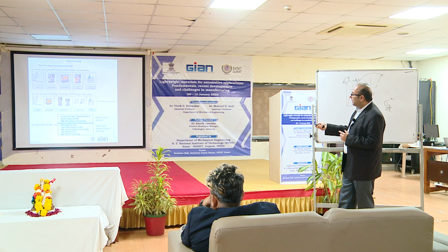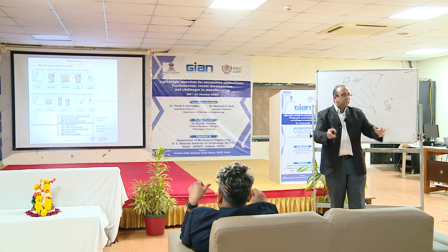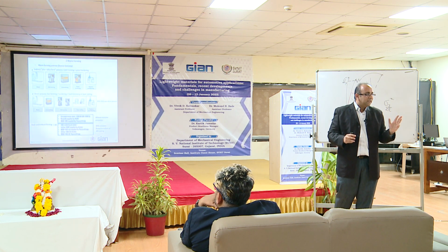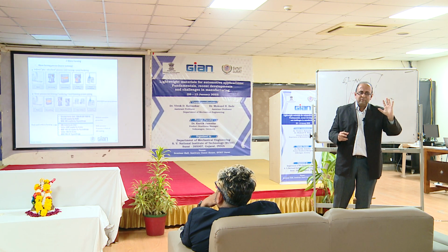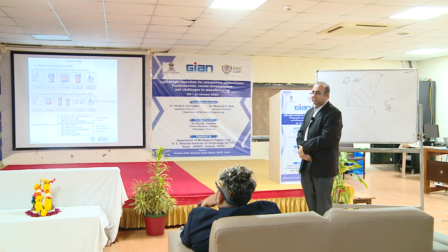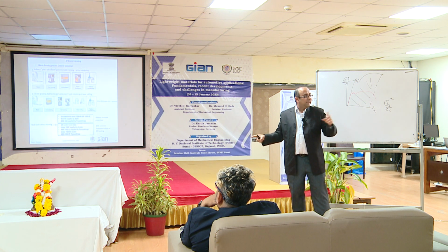First you have this part. You don't do warm forming. First you deform the part. Make it a complex part, cut it, everything. It is a soft part. 300, 500, 350 I said. It is the yield strength. Very soft part. You can cut it, you can do everything. You can give complex shapes. Then you send it to the oven. Make it into austenite.